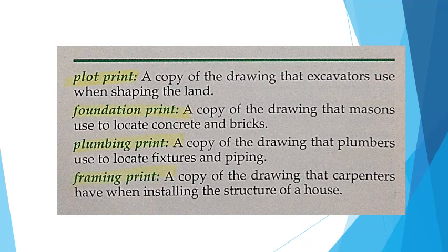These structural details will help you determine where to run the cable and conduit in a manner that reduces the number of holes in the joists. Drilling these holes takes time, and the holes may reduce the strength of the joists. The floor plan is a useful print when you must locate outlet receptacles and switches within the rules of the NEC.